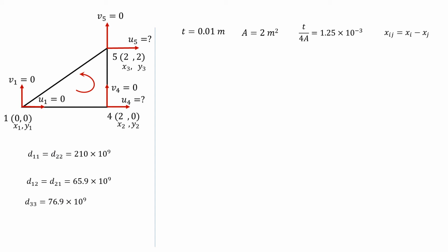Okay, in order to determine the terms A, B, C in element 2, again, we have to refer back to the element connectivity of element 2 in order to get the values of x1, y1, x2, y2, and x3, y3 for element 2. We also need to refer again to the calculated properties D11, D12, and etc., which are constant for both elements.